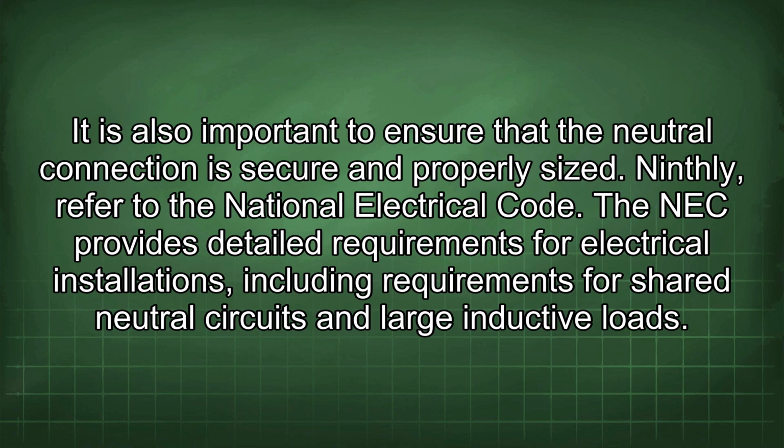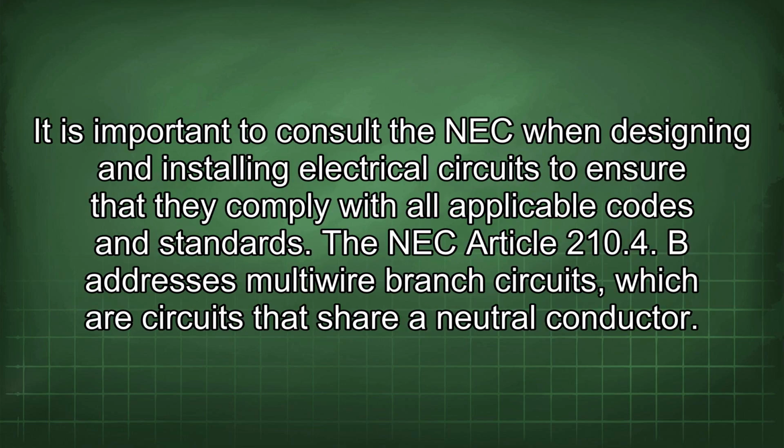Ninthly, refer to the National Electrical Code. The NEC provides detailed requirements for electrical installations, including requirements for shared neutral circuits and large inductive loads. It is important to consult the NEC when designing and installing electrical circuits to ensure that they comply with all applicable codes and standards. The NEC Article 210.4 addresses multi-wire branch circuits, which are circuits that share a neutral conductor.